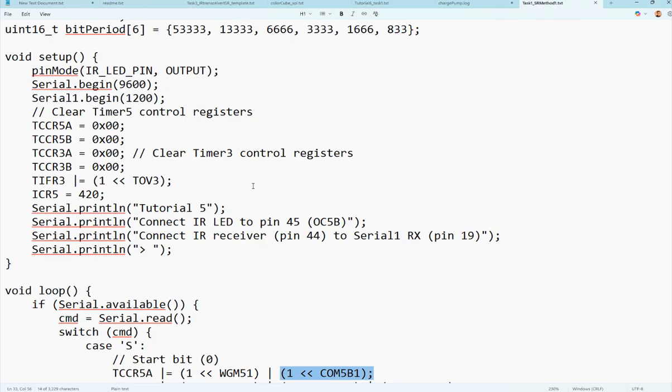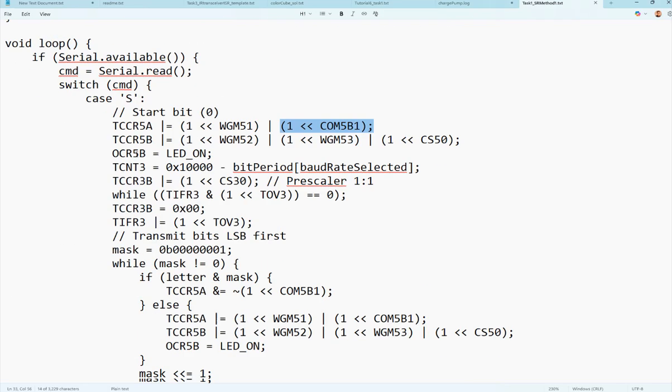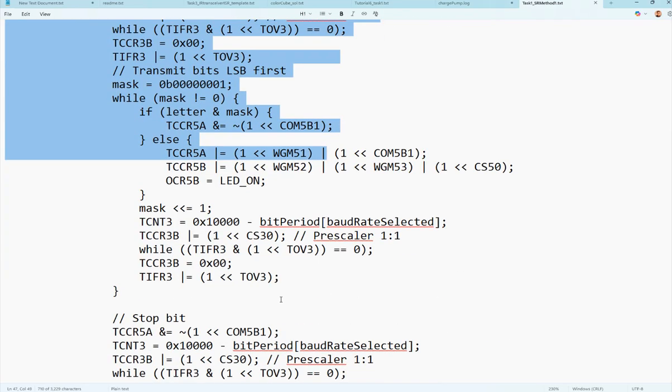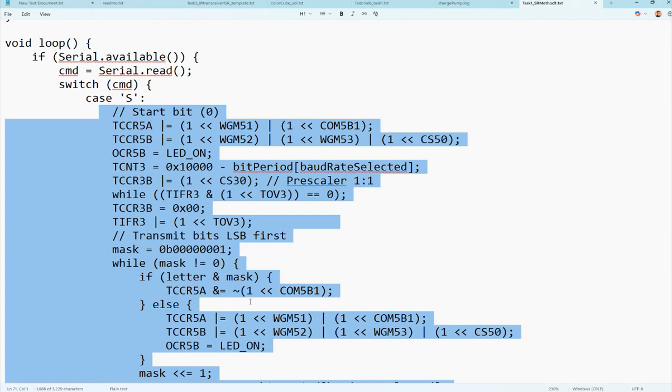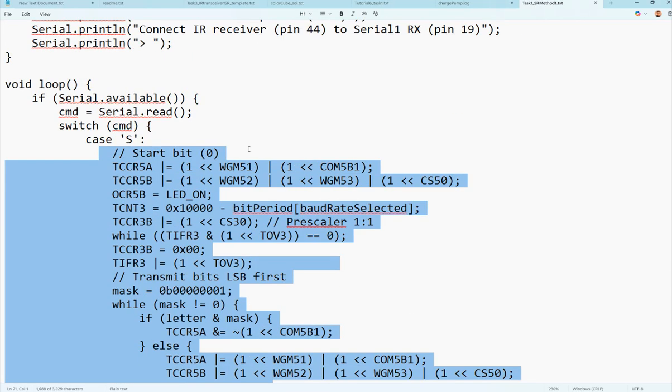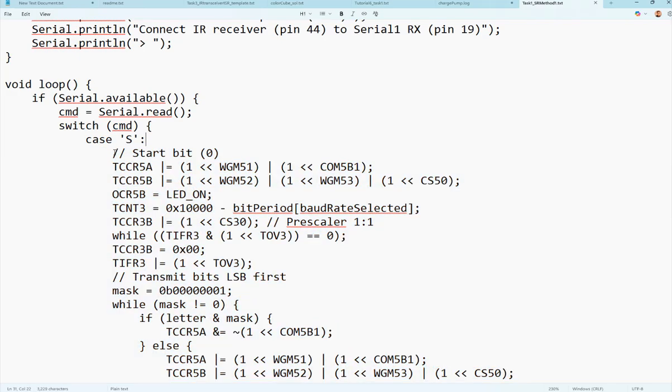It's going to be in the ISR. So all the S, you see what I'm doing here for the S, should be placed in the ISR and should be modified a little bit. Okay? So you press S, there's nothing else to be done. You just give a true to a flag. You can name the flag whatever you want. Just transmission to be true, and then whenever it interrupts, it will detect the flag and get into the idle and jump to the next state.